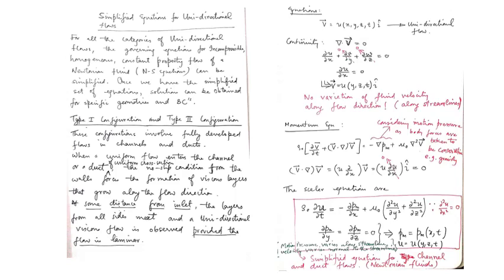And this is the major advantage. Why? Because after all, this is the nonlinear term which imparts the complicated nonlinear character to the Navier-Stokes equation, which makes it so hard to solve. So once this convective term is 0, we expect that the Navier-Stokes equations would now be much simpler and easier to crack, or to solve.